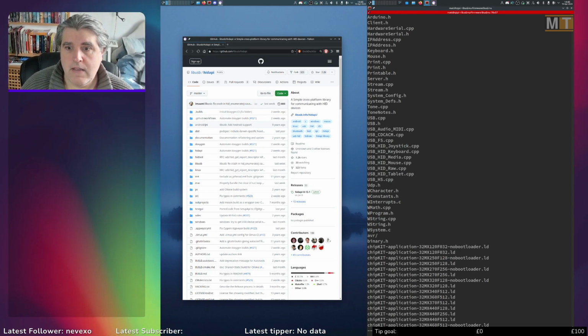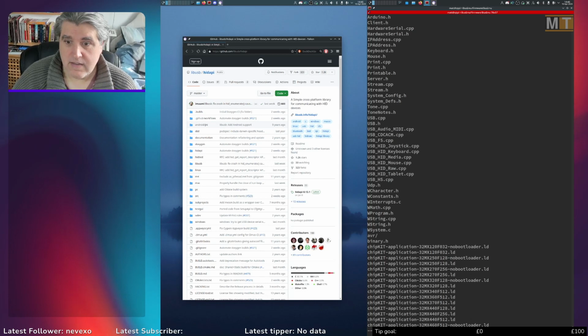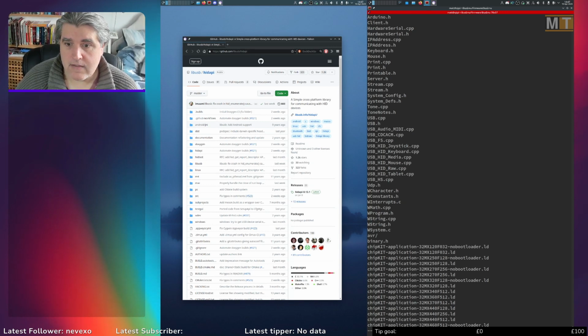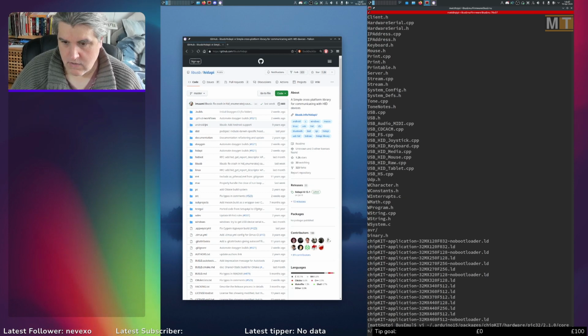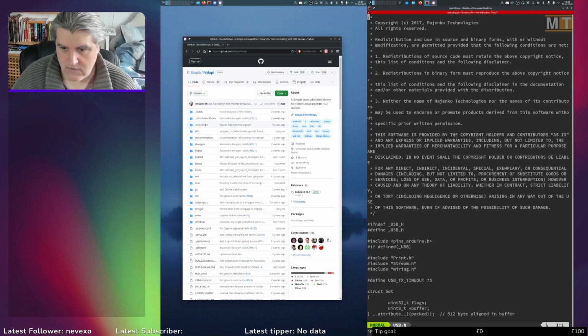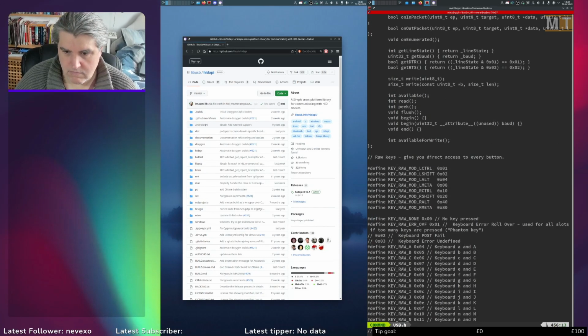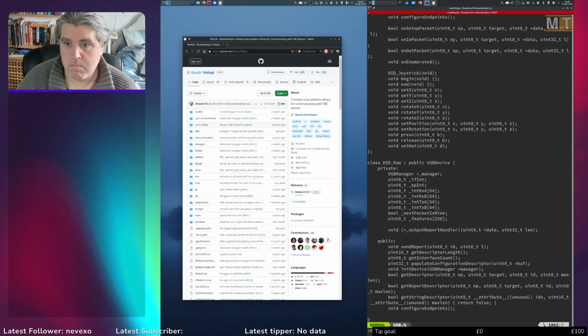We've got audio, MIDI, CDC, SCM, file system, HID joystick, HID keyboard, HID media, HID mouse, HID raw, that's what I want, HID tablet, USB HS, everything you could imagine. Okay, so HID raw, but if I just look in USB.h, that's got everything that you need. But if I now look for raw, no. HID raw, there we go.